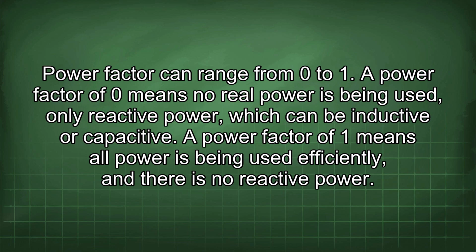A power factor of 0 means no real power is being used, only reactive power, which can be inductive or capacitive. A power factor of 1 means all power is being used efficiently, and there is no reactive power.